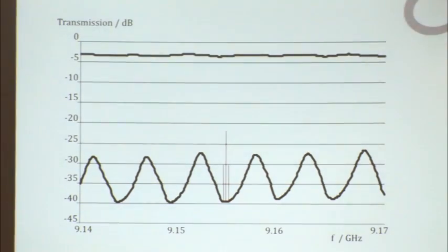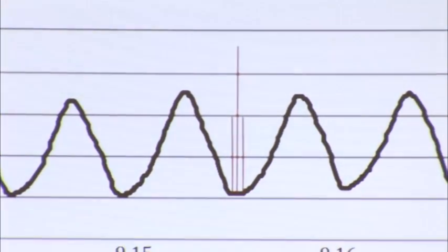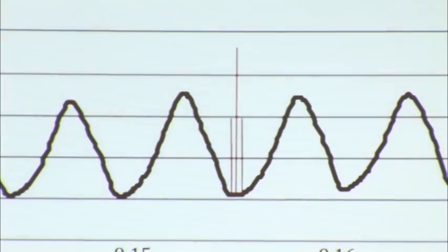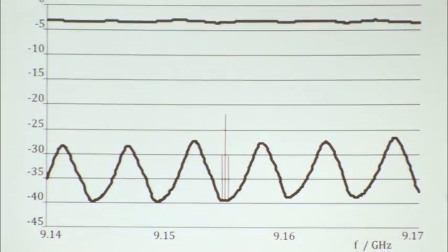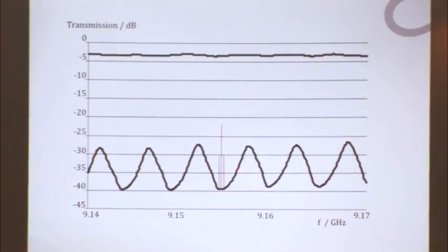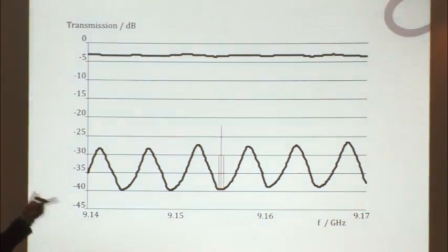And again, for the sake of completeness, so that everybody understands what I'm doing, I have the carrier frequency, I have the lower sideband, I have the upper sideband, and I just make sure that this is really within the minimum of the transmission. This is happening at 9.15 gigahertz. Just to point out, if I was using a higher carrier here, I would not observe that desired transmission. And the next problem, if I use a slightly higher frequency, I would have signal distortion, because that behavior also corresponds to the group delay. I'm not showing that in this presentation, but if the scale was the group delay rather than the magnitude, it would indicate, and this is what the analyzer really tells, 0 seconds, and it would here tell 100 nanoseconds, because this is what directly corresponds to 20-meter regular transmission at the speed of light.